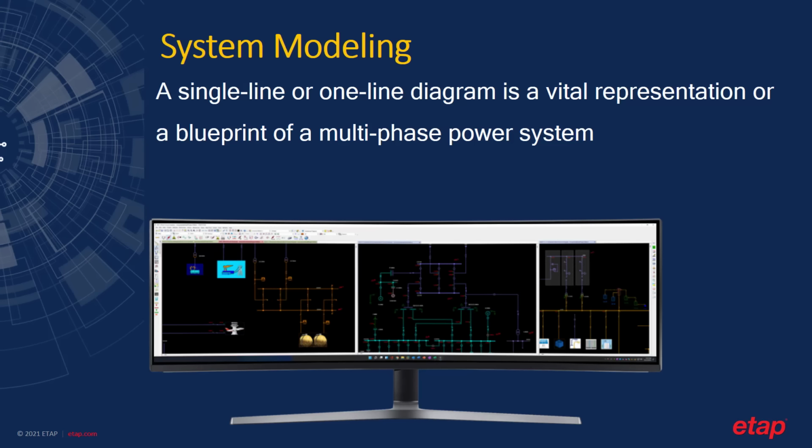and industry. In power engineering, a single-line diagram is an electrical drawing representing the electrical devices or assets of a power distribution system. The electrical diagram is represented by symbols and describes how these electrical devices are connected and related. Sometimes a single-line diagram of an electrical installation is also called a one-line diagram. The single-line diagram provides a fundamental representation or a blueprint of a three-phase power system. As the term suggests, it's a one-line diagram that uses a single or one line to represent all three phases.